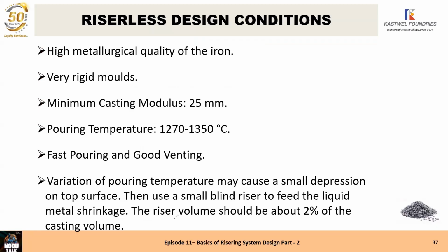Under what condition can we make the casting without the riser? We have seen the pressure control risers with the riser. We have seen the bottle riser casting with the riser. Now we'll see riserless design. For riserless design, you require high metallurgical quality of the iron. The metal should be of high metallurgical quality. It should be poured into very rigid molds, properly clamped and hard.